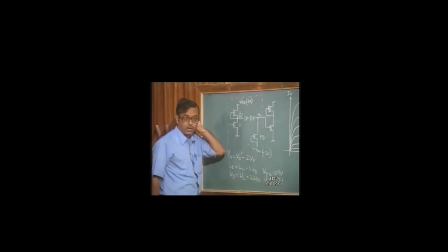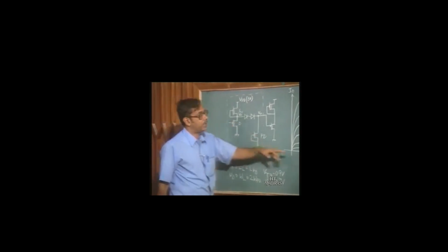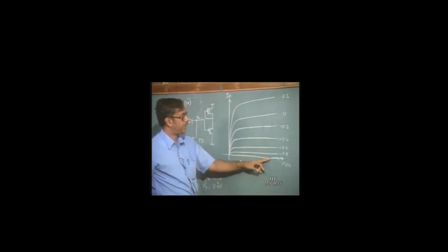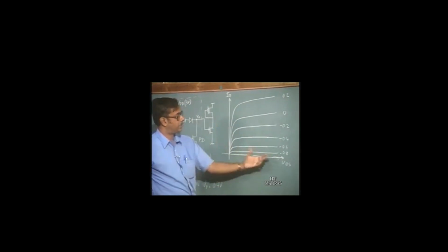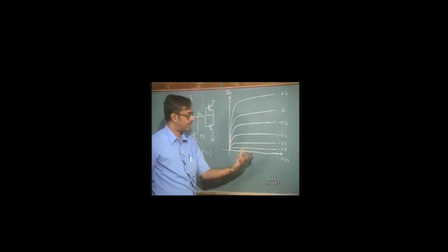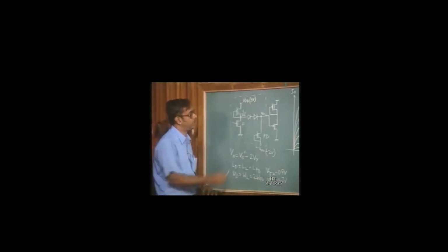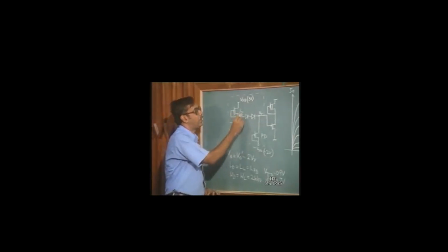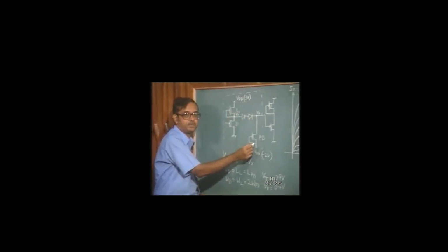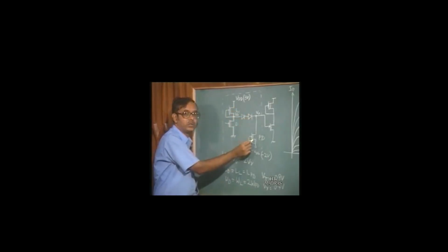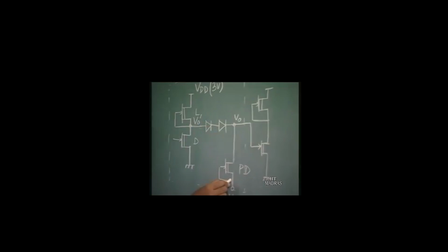structure? Now, normally what we do is we draw the characteristics of the load device, starting from VDD here and inverting it along the x axis. But here there is a small difference: because of this pull down structure, a level shifting structure, a current is constantly going to flow through these devices.